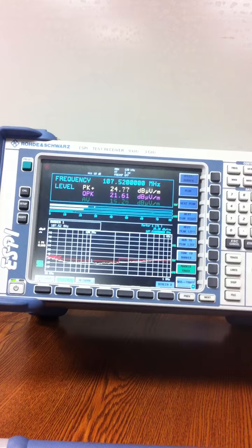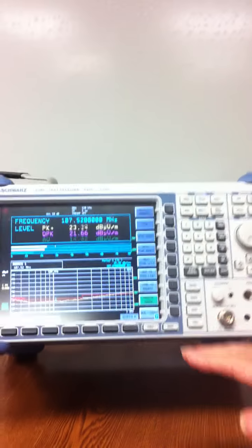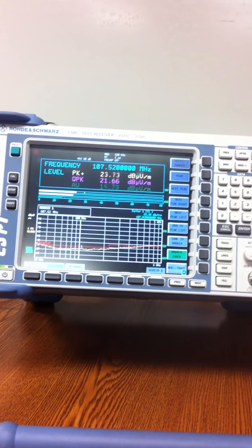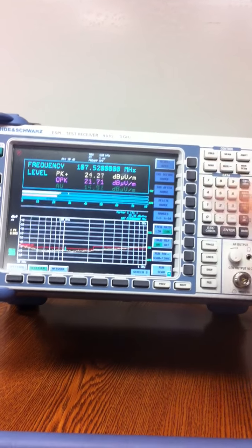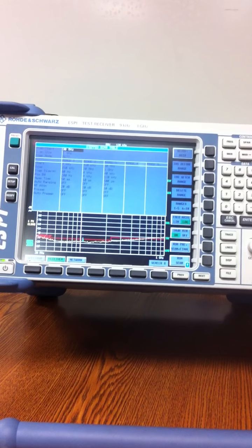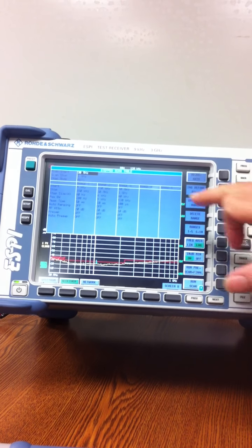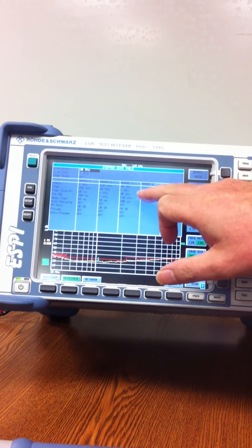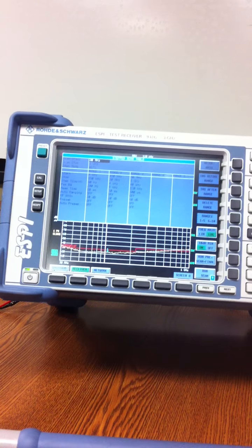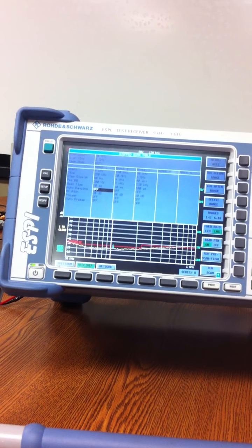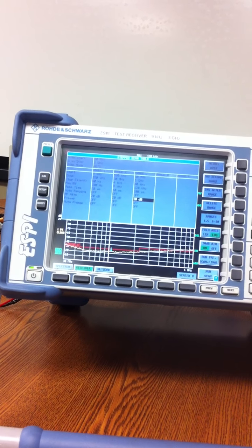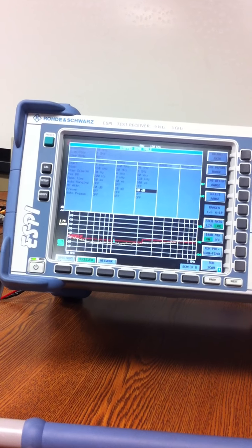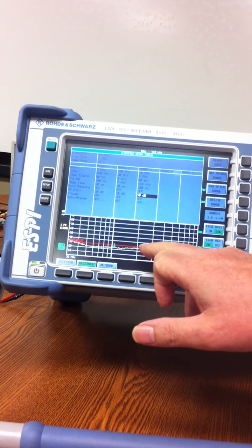And I will show you the difference between the different amplification modes. If you go to sweep mode, and go to scan table, you will get an idea about what is done in the frequency range you are using. Right now we are in the 30 megahertz up to 1 gigahertz range. Just go down to those values. And you see there is an RF attenuator that is set to 10 dB. Just remember where the curve sits right now.